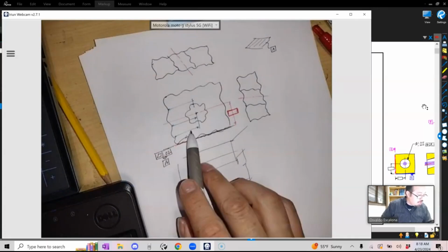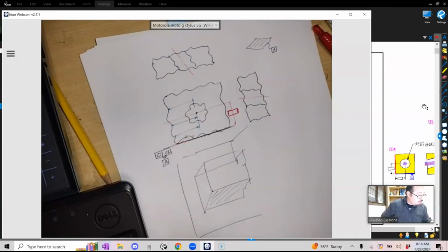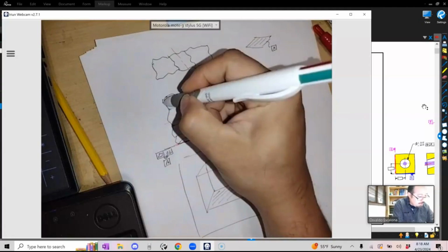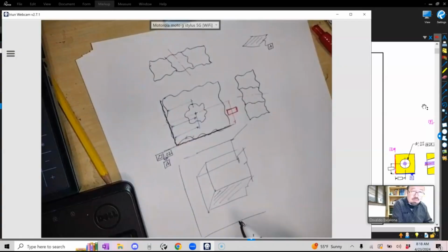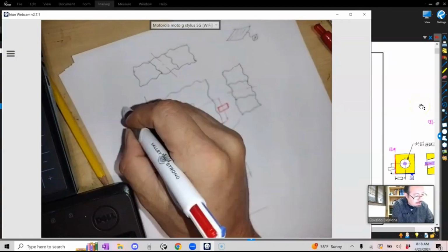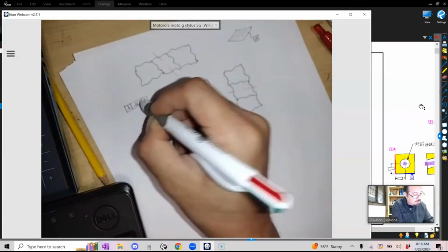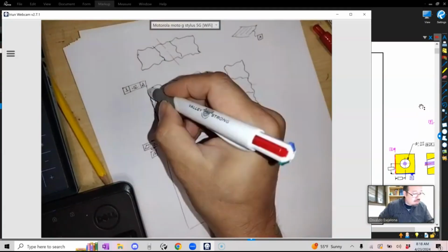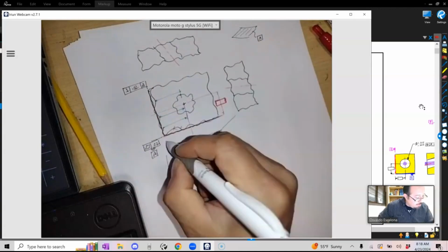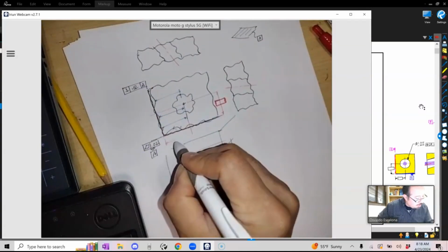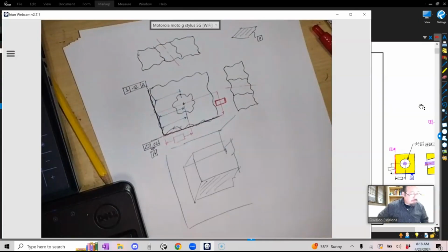I also got to take care of the left side as well as the back side. So most likely I will want to make this perpendicular, right? So this can have a better, more stable condition. I'm going to make this perpendicular to datum A, 0.2. It's a little bit better. And now, instead of measuring from my imperfect condition, I can start measuring from the perfect condition, right? From the perfect condition.